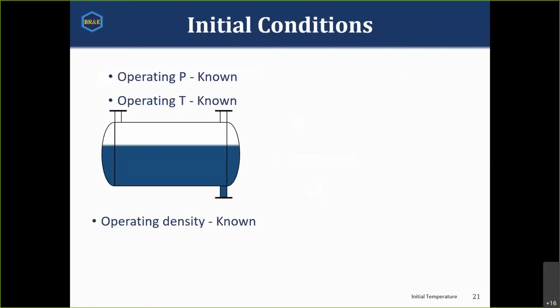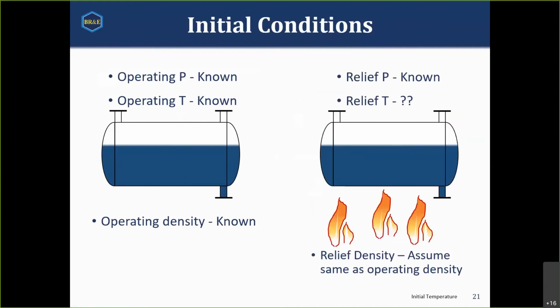It assumes we know our operating pressure, it knows our operating temperature. If you know how much your vessel is full of, if you know your operating pressure and your operating temperature, you therefore know your operating density. That's because you know your composition, you know temperature, pressure. The fact that you know your density is very important, because we are going to assume that the density stays the same once the fire breaks out. We might be tempted to say our density changes. So let's talk about this. I think this is well worth discussing.